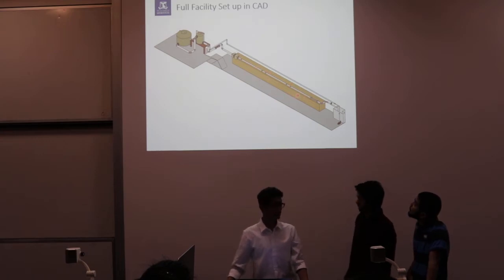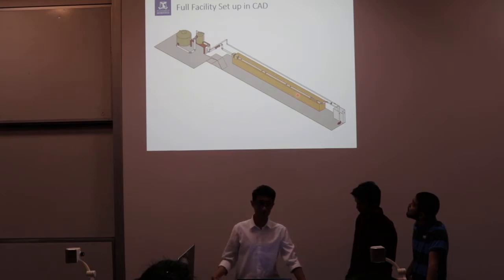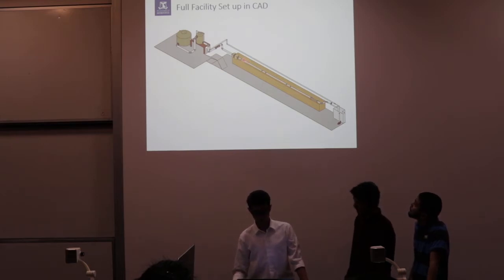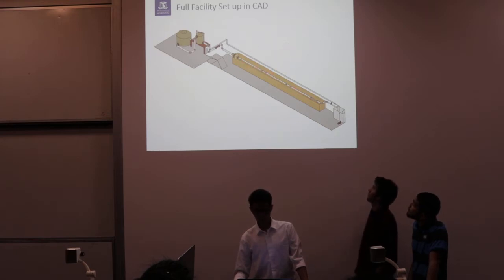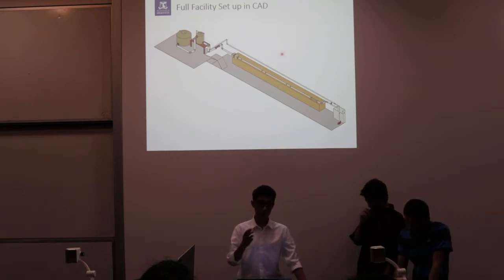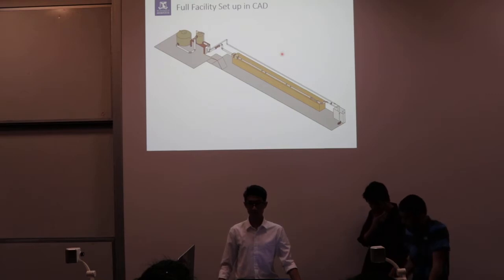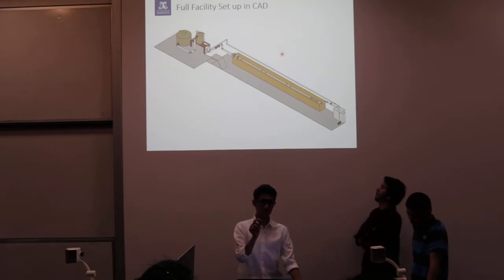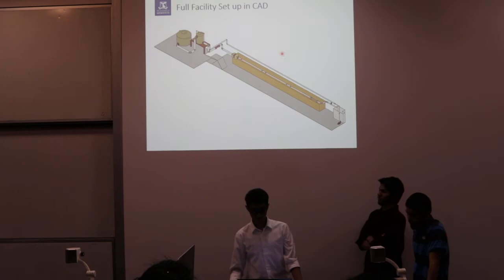Because we're using a differential pressure sensor, we're going to connect one pressure tap to one end of the pressure sensor, and then the 9 other taps, which are 1 meter apart from each other, are going to be connected to the other end of the differential pressure sensor. What that sensor does is calculate the difference in pressure between the first pressure tap and the second pressure tap.